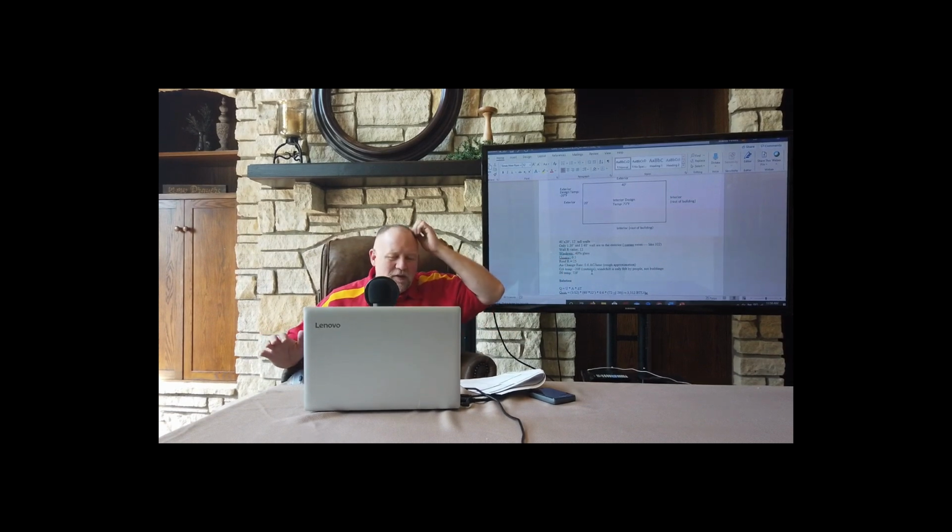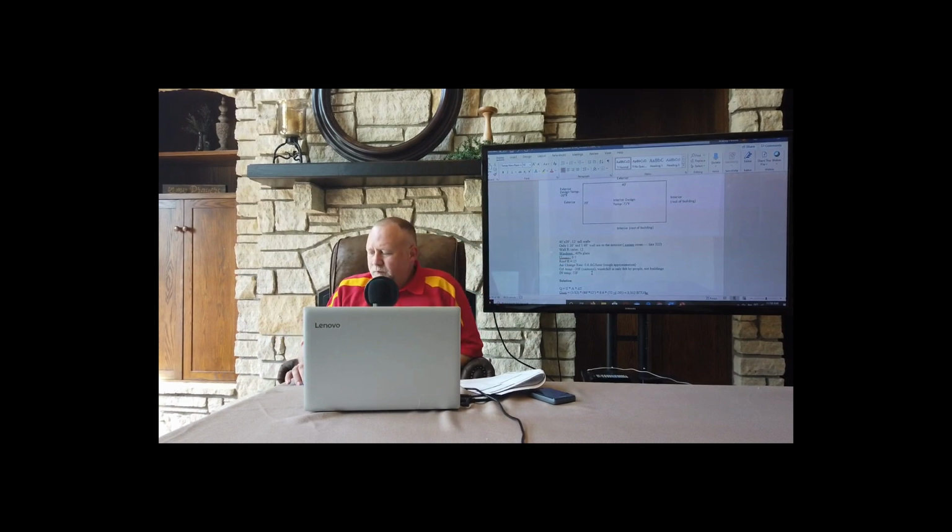40% glass on the windows. I put 40% because the Energy Code only allows you to do 40% glass maximum on an exterior building without offsetting. If you have more than 40% glass, you're going to have to offset that extra energy use with improvements elsewhere. Like it's got to be much better than a code minimum piece of glass. You might have more efficient boilers and chillers and lighting systems, those types of things.